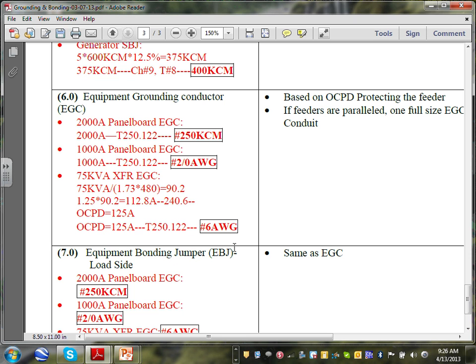So these conduit methods will eliminate the need for this type of conductor. A lot of us, guys, if you are using a feeder, we like to pull an equipment grounding conductor anyway with it. Any comments about the 250 kcmil equipment grounding conductor? So that's the first calculation, guys, for the 2000 amp. The second 2 calculations, I'll go over them for a different panel.